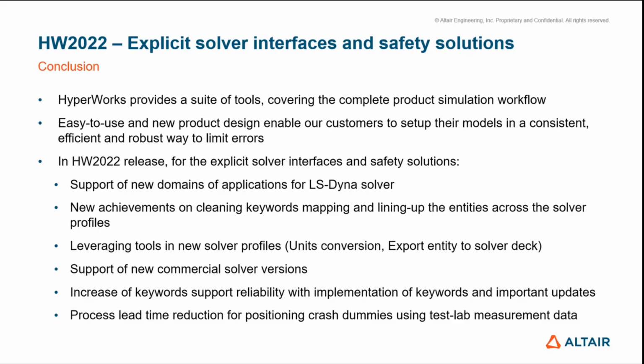And in the 2022 release, for the explicit solver interfaces and safety solutions, those are the points that I have mentioned in my presentation. So first, the support of new domains of applications for the LS-DYNA solver with the implementation of frequency domain keywords for NVH, acoustic, and durability simulations.